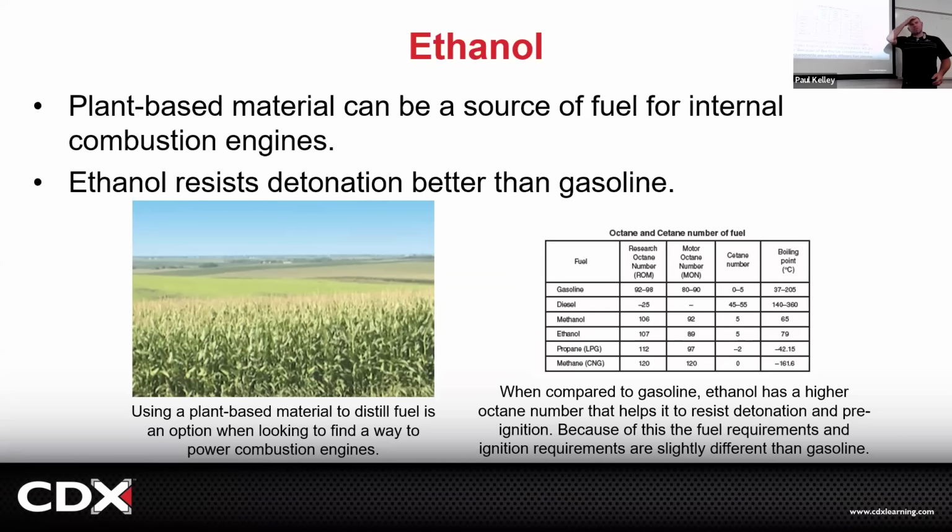Here's the negative, though. There's actually less energy. There's fewer BTUs, British thermal units of energy, within the ethanol. So you're going to have to burn a lot more ethanol than you would gas to hit the right numbers, to have your emissions levels correct, and control your combustion temperatures. So it's better fuel when it comes to high performance and being able to advance the timing and having the fuel not pre-ignite. But if you had a car that would go 300 miles on gas, it's probably only going to go 200 miles on ethanol. So is it better in that way?